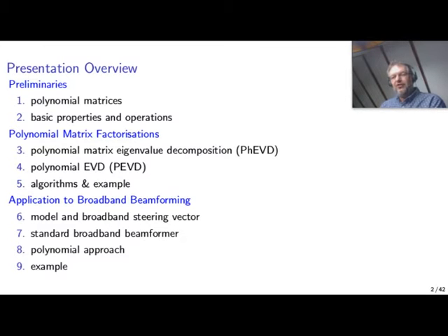In order to formulate and solve broadband multi-sensor problems, we need a factorization similar to what you know as a standard linear algebraic tool such as the eigenvalue or singular value decomposition. So the second part of this talk will be focused on decompositions of a particular type of polynomial matrix that we encounter in a lot of these problems.